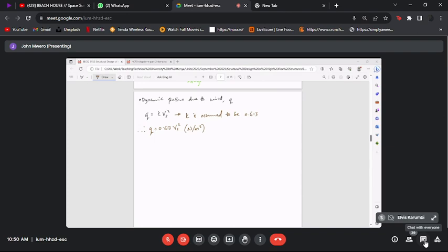What will happen is that eventually, you see, like a building like this, we call it a U block. Each floor will have a different force for wind, which we will apply at every floor. So the first floor will have a certain wind force that will apply at that level. When we go to the next floor, the wind force will be slightly different, and we'll apply that force at that floor, like that for all levels.